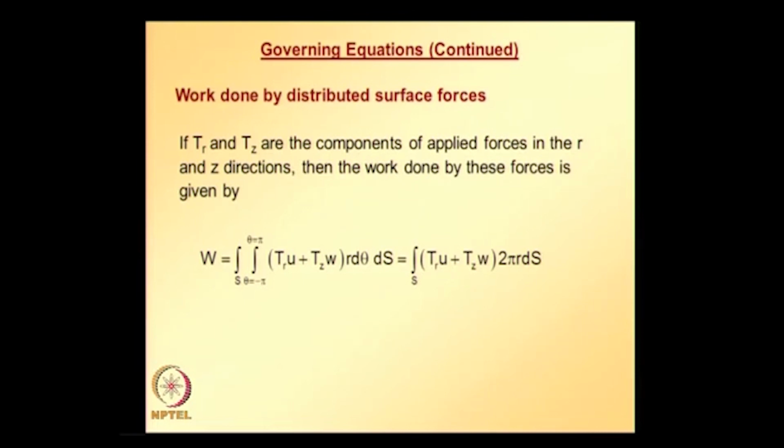We need to evaluate the integral given in this equation, which is displacement in the r direction times traction in the r direction plus displacement in the z direction times traction in the z direction, and the entire thing times 2 pi r, over the edge over which the distributed force is applied. If specified concentrated forces or body forces are present, work done by these forces can be calculated in a similar manner.